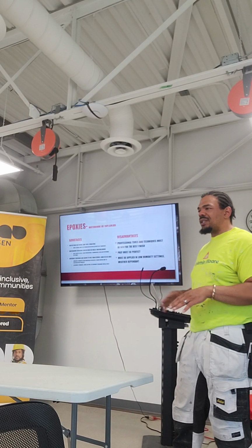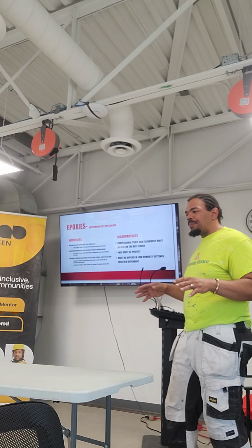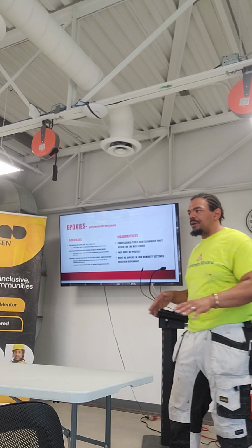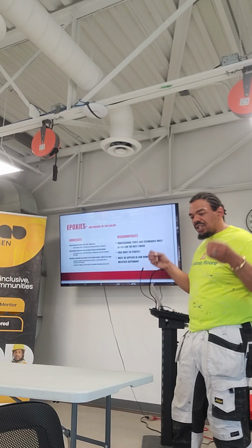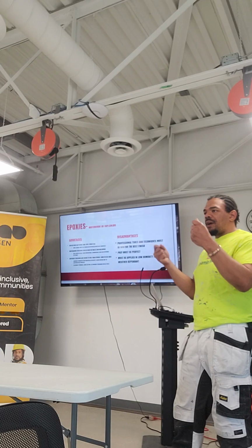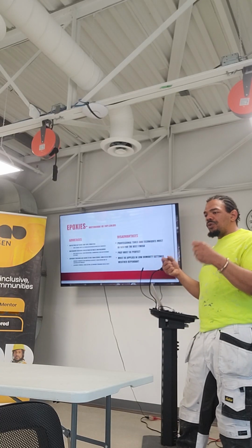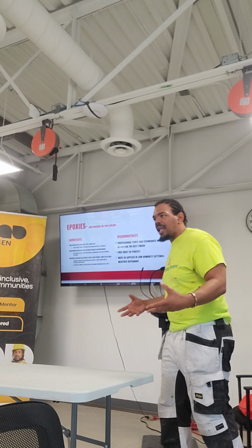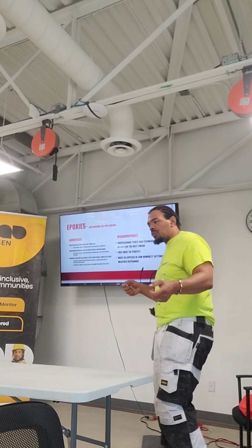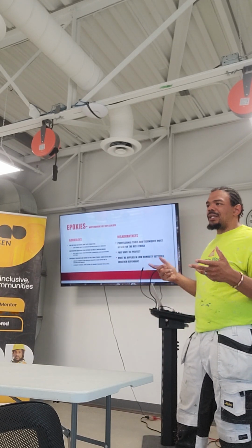I vacuum the floors 6 times, and we wipe the floors down with lacquer thinner. So we do a lacquer thinner mop. I use lacquer thinner because it soaks in and emulsifies, it pulls dirt and grime out. So anything that may have been embedded into the floor from us grinding it, the lacquer thinner will pull it up, and then we can wipe it down, and it dries like that.